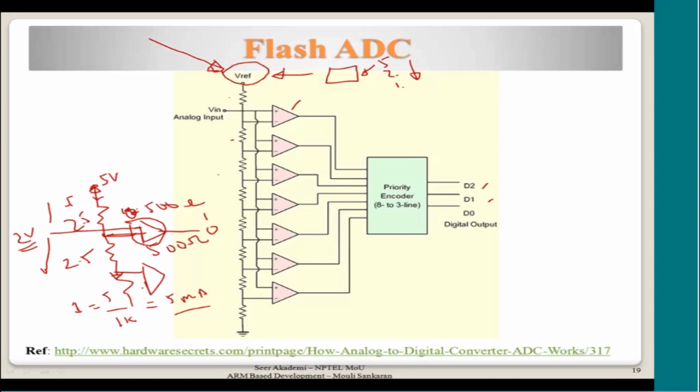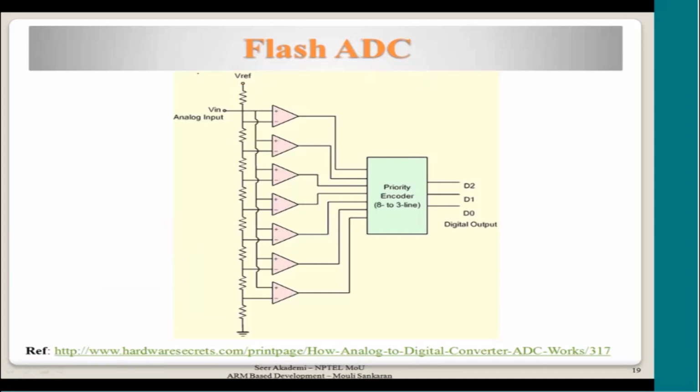So you can basically understand that if I put more resistors here, dividing this 10 volts, and 10 resistors are there, maybe of the same value, then I may be dividing it into 1 volt each. Then I will give a range of values 0 to 1 volts, and if it is an input, then it will generate from 000 to 111. So it may generate some values.